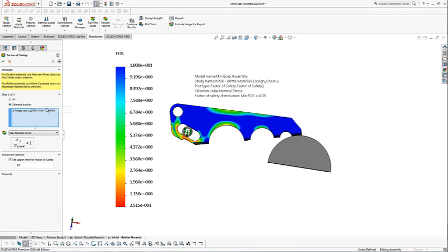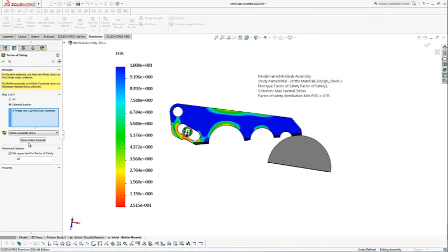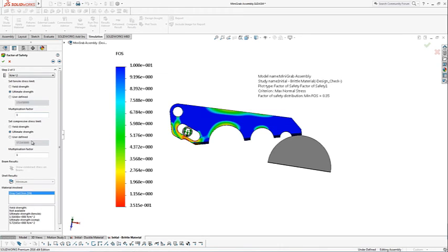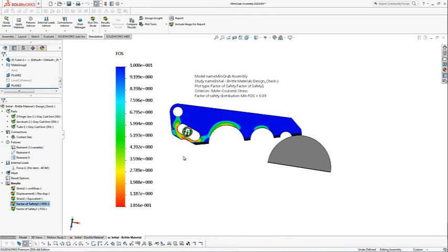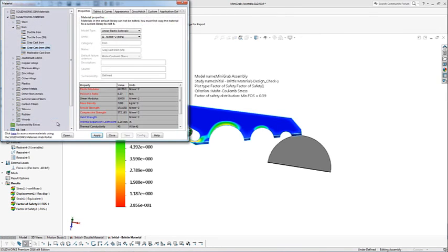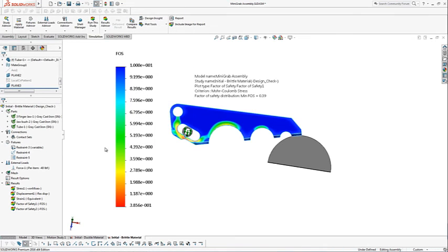And, you know, alternatively, I can come up here and say I want to use the column stress, Mohr column, and in that case, it's going to ask me to specify the ultimate tensile strength and the ultimate compressive strength. And you can see, because I either specify those manually or it pulls those directly from the material property definition. Let's plot this real quickly. You know, they're both around the same, 0.35, 0.39, but remember when we talked about brittle materials, the ultimate tensile strength is going to be much smaller than the ultimate compressive, which is exactly what we've got here.